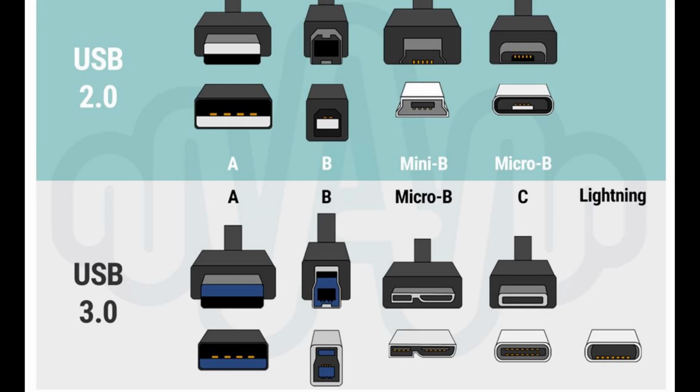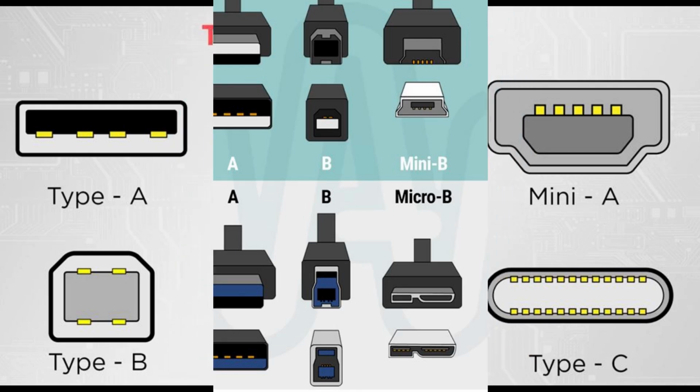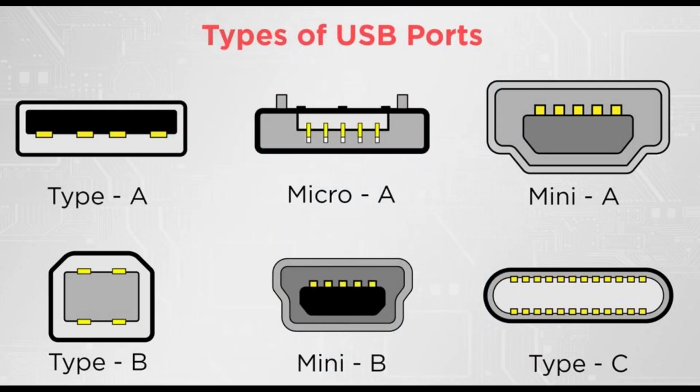The Type C connector, also known as USB-C, is not exclusive to USB, is the only current standard for USB, is required for USB 4, and is required by other standards, including modern DisplayPort and Thunderbolt. It is reversible and can support various functionalities and protocols, including USB, some are mandatory, and many are optional, depending on the type of hardware, host, peripheral device, or hub. USB specifications provide backward compatibility, usually resulting in decreased signaling rates, maximal power offered, and other capabilities.